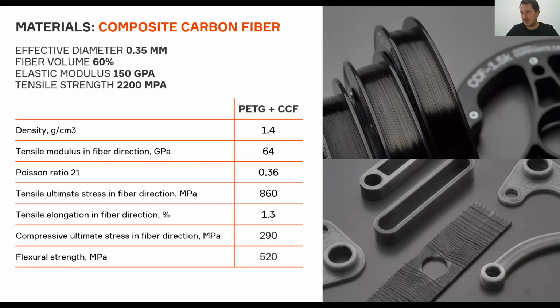Most of the materials, such as nylon, such as the PA or PETG, would not work over 100 degrees, but there is a slight increase of the performance at high temperature when printed with fiber. But normally you should check the properties of the plastic, what is the maximum using temperature.